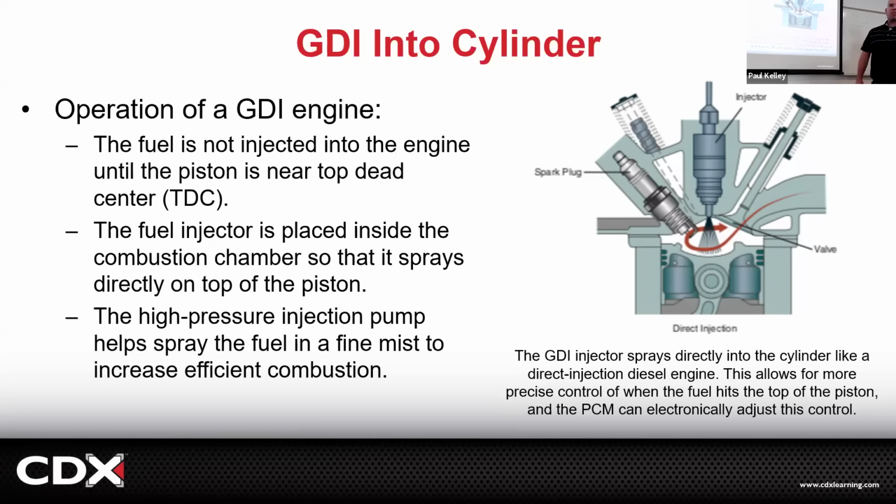But there's another benefit. If we have really high pressure and we have really tiny holes in the injector, it can spray a really, really finely atomized mix. That's better for emissions. That's better for power, right? It's just going to be better for combustion. We like that. But the negative, like I was saying, is that now the injector is bigger, stronger, more powerful. It can sometimes take higher voltage to open and close. Sometimes we'll use piezoelectric crystals to actually open and close the pintle.